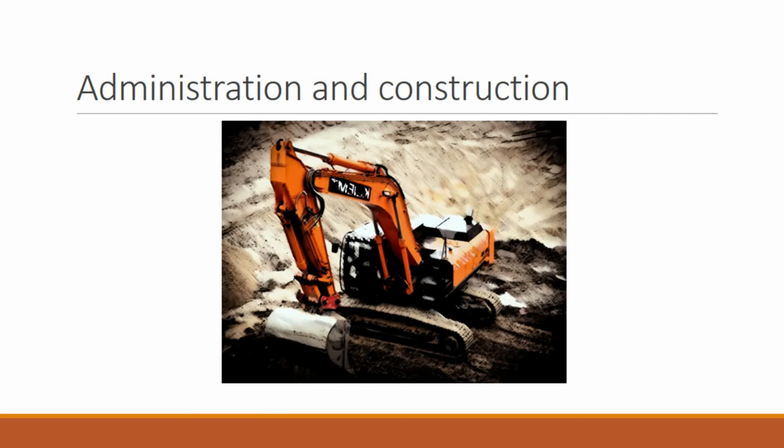Issuing clear contractor procedures and rules and training each employee individually is also important when you issue work for construction. Projects should hold regular construction meetings to discuss any updates and problems that arise. Payment requests are often made on a monthly basis and should include a retainage, which is around 10% until close to project completion, to cover any construction issues.